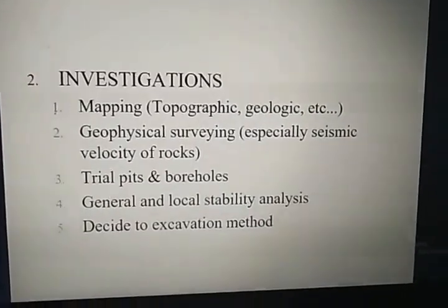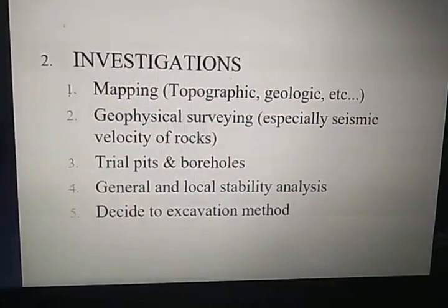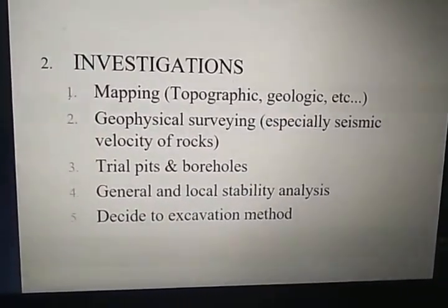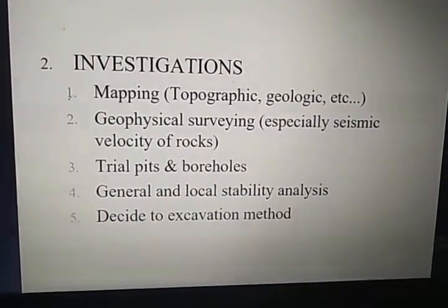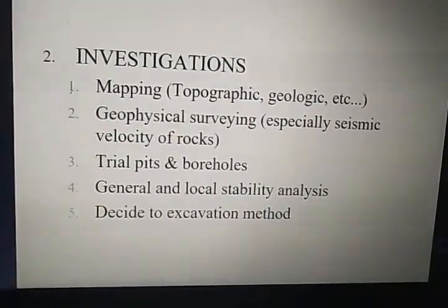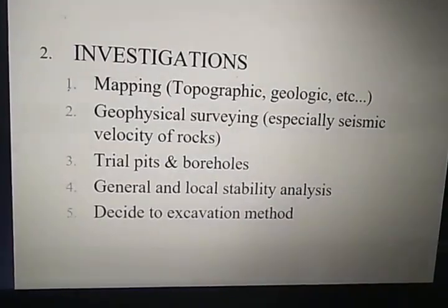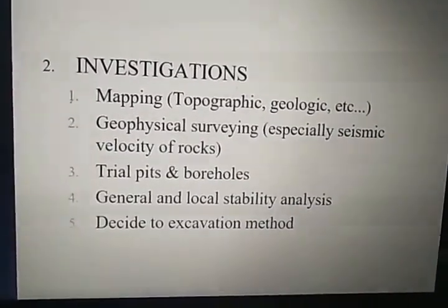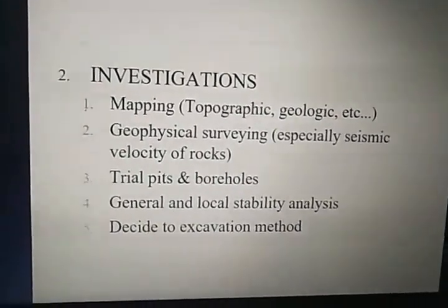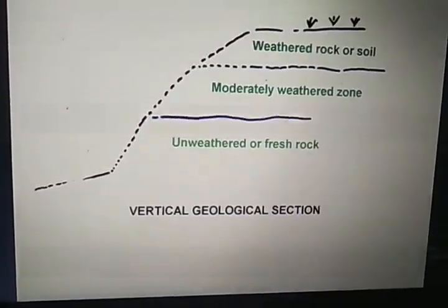Investigation: again we have to move towards the investigations. Which type of investigation do we require? We require a topographical map, a geological map, geophysical surveying, and trial pits and boreholes taken at certain intervals. General and local stability analysis we have to do. Decide the excavation method, whether manual or tunnel boring machine. So there are different methods.